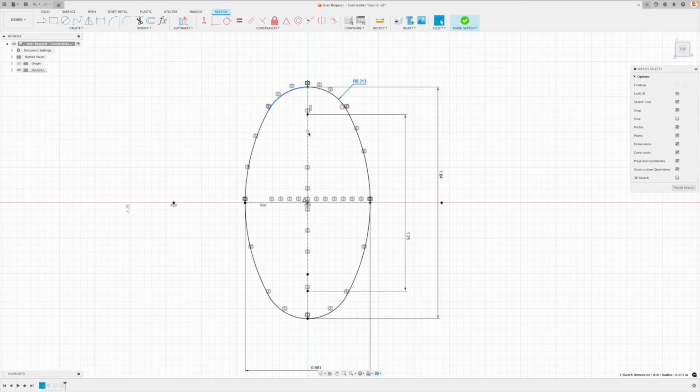We know that the center point is locked. This arc right here, when we lock the center point to it, it became fully constrained. Well, why? And this is one thing with math as well, is that if we know two elements of three, we know the third. In this particular instance, this arc, we do know a bunch of different things. We know its start, we know its end, we know its center point, we know its arc value, its radius value.